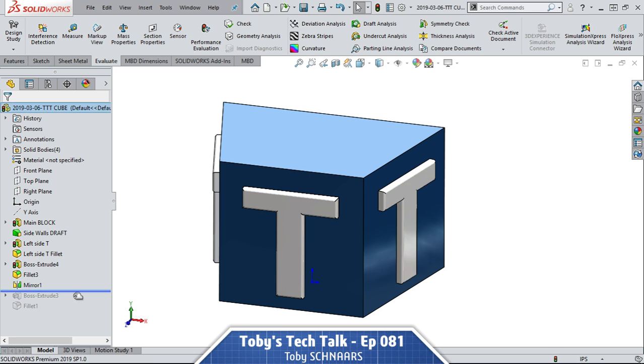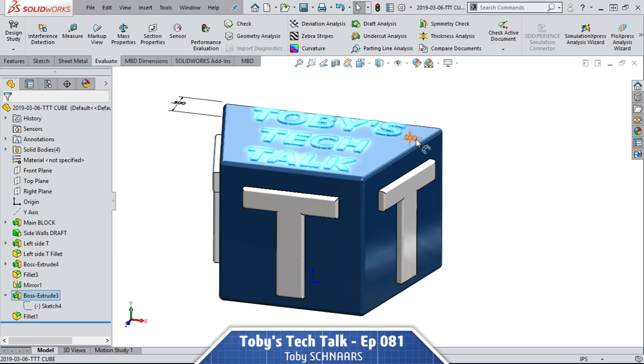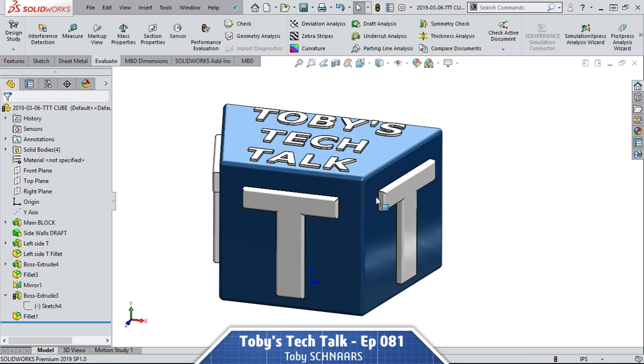See, Control-B is only going to rebuild downstream features. So for example, if we were to go to this last feature here in the tree and make a change to it, let's say I change it from 30 thou to 20 thou, and then we do a Control B, only that feature and maybe something downstream are going to get rebuilt. Everything else above it in the tree is not going to be rebuilt. None of these features have a rebuild light, and none of these features are a child of this feature here. So if I do a Control B, only that feature is rebuilt. But when I do a Control Q, the entire tree gets rebuilt.